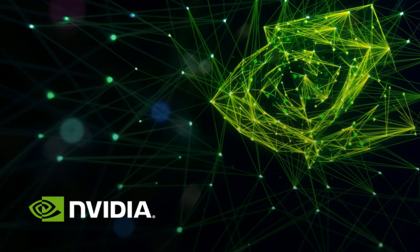The nice thing about these models is that you can use the TensorFlow object detection API to train them for your own tasks. If you make your own dataset with a bunch of bounding boxes, you could train on that, and then you'd have to use one of those models for the tools that we have in the JetBot project. But if you use one of those model architectures, you could train it to detect whatever bounding box you want, and then you get basically 14 or 18 FPS, depending on which model you're using, on the Jetson Nano.